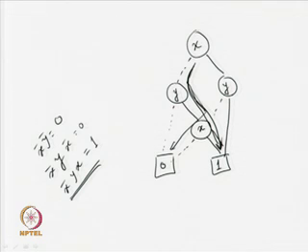So, though our basic definition of BDD is not restricting the occurrence of variables any number of times in any places, we may face problems. So, in that particular case, what happens? We have to come up with the notion of consistent parts, and when we look for the evaluation of this particular Boolean function, it should be evaluated through the consistent part only. We should not evaluate it through an inconsistent part. So, that is why this is one inconsistent part, because here x equal to 0 and x equal to 1, which is inconsistent.